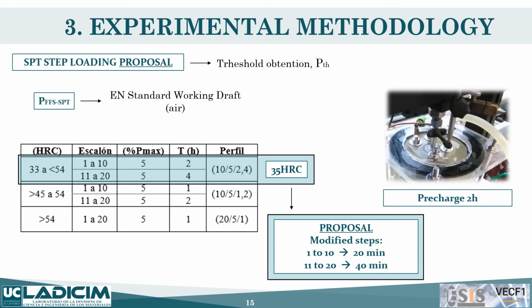In our case, instead of 2 and 4 hours for the first 10 and second 10 steps marked by this standard, we choose a modification of this duration that will be 20 and 40 minutes. Why? Because as the specimen is much thinner, we have proposed that the time must be much less.